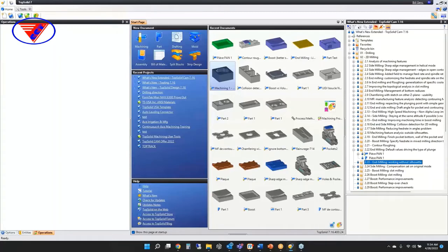For example, in the case of a very high face count part, where the finished machine zones could be defined directly by the selected face. Prior to using this possibility, be sure to check the following. Activate default values, TopSolid Basic, no stock management, or finish environment, collisions, etc. Deactivate the preview of the toolpath. Deactivate the graphical preview of the machine zone. The faces to work with on your part are all cleared on the sides, devoid of risk of collision, and they're contouring to find the machine zones by themselves.